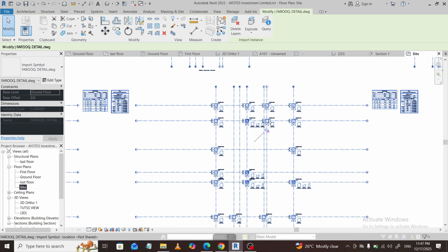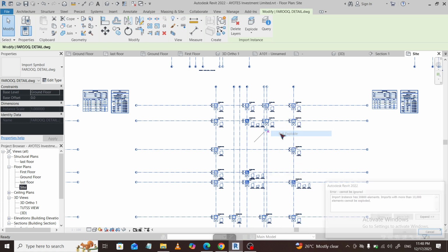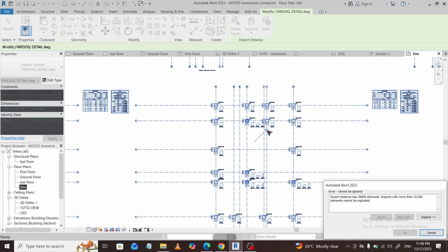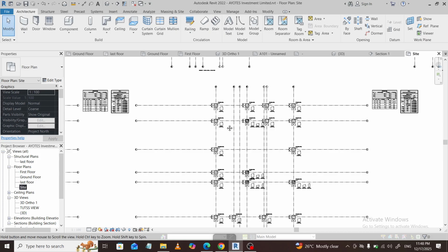If the line work looks heavy or inconsistent, consider reassigning line styles to match your project standards. For filled regions, confirm that the fill patterns and boundaries are appropriate, and remove regions that are only visual noise. Lastly, give the view a quick pan and zoom to make sure everything reads clearly. With that, you've converted your CAD import into workable Revit elements and cleaned up the graphics for a more professional result.